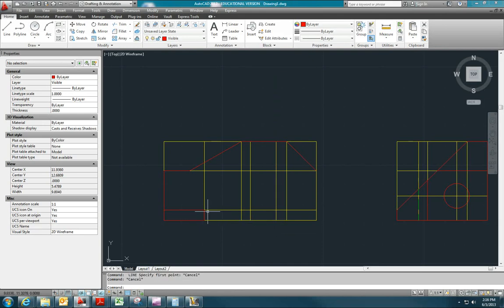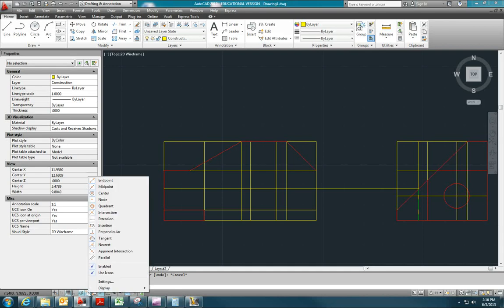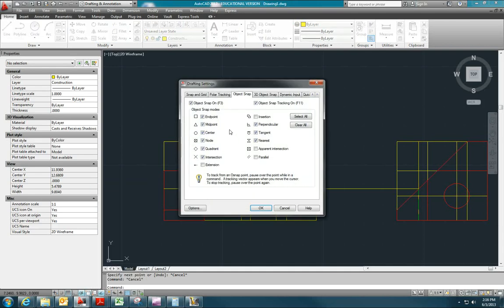Then you have this 1.14 area. Now, the 1.14 area is where it's recessed back by 0.54, which is from this hidden line. So again, let me go to my construction layer. I'm going to go to the top of my hidden line and project across until I see my perpendicular object snap. If you forgot how to turn these on and off, you just right click on the object snap button, go to settings, and perpendicular is checked. That's why I'm seeing that now.